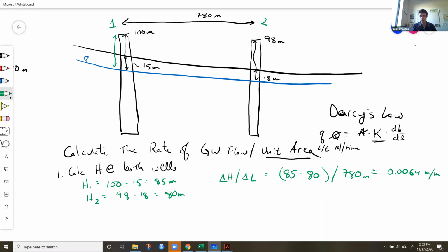Based on the soil texture, maybe you take it back and do more of a grain size analysis or something like that. So you can say the texture, and then from the texture, you can look in a table and say, okay, loams have a hydraulic conductivity of about 10 to the negative 2 meters per day. So this is something we can look up, and you could do a sensitivity analysis as well on this, plus or minus a factor or an order of magnitude or something like that.